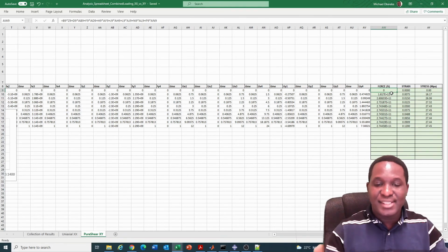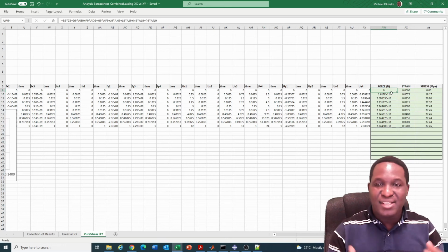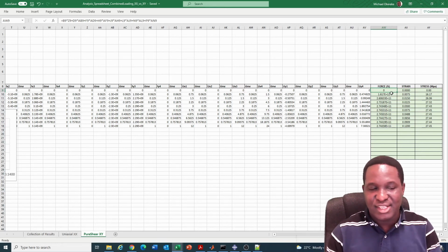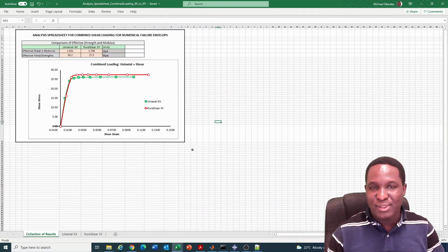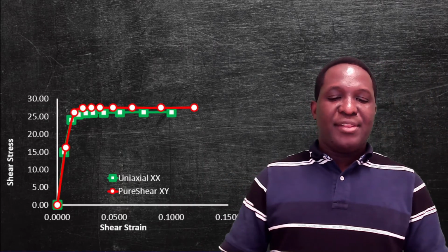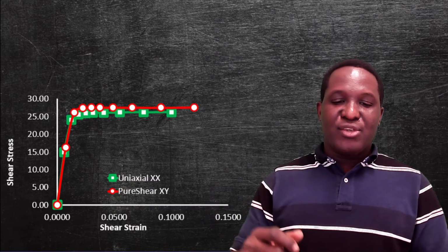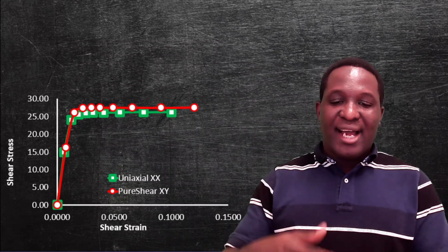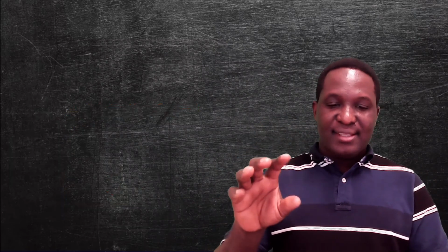So you use the same data that's taken from the simulation you've run, and you're plotting the stress trace as well as the uniaxial stress as well as the shear stress trace. And when you plot them and put them all together, then you could see what's happening, the result. So now we finished running and setting up the model and generated the stress strain data. And this is the stress strain data. And you can see in the stress strain data, there's a combination of a uniaxial deformation in green and a pure shear deformation in red. And we extracted the values from those.